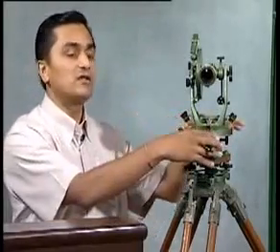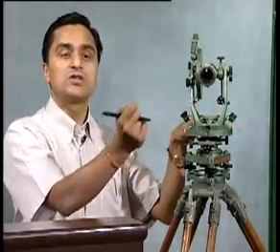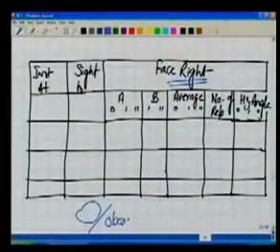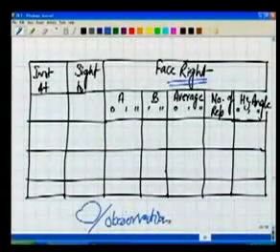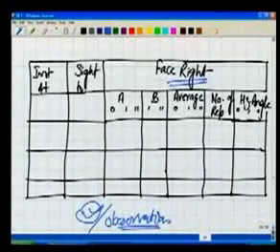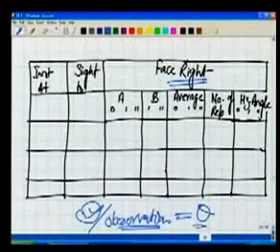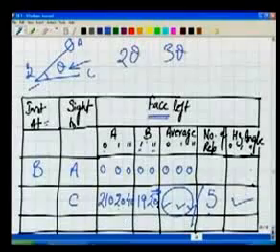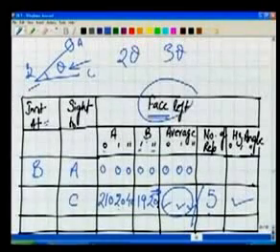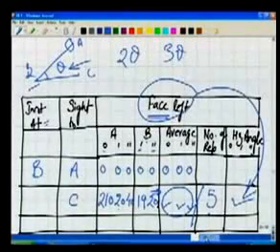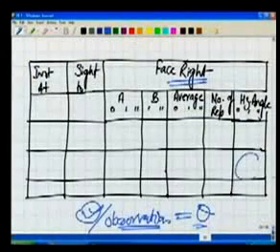So what I am doing, mechanically I am adding the angles here. Mechanically, just by using it, theta, 2 theta, 3 theta, 4 theta, 5 theta, and mechanically I am adding the readings, and the final reading value divided by how many observations were there gives me the angle value, theta. So we have now from our previous table the angle for face left, and as well as from this table angle value for face right.